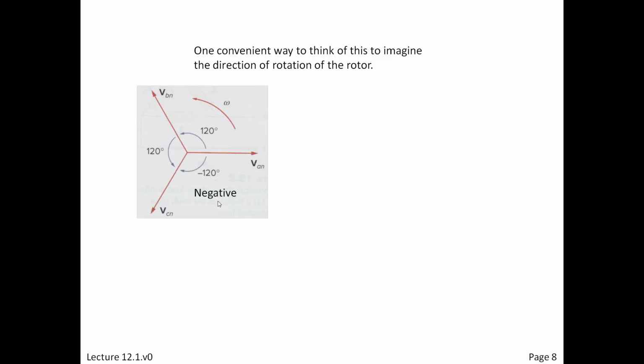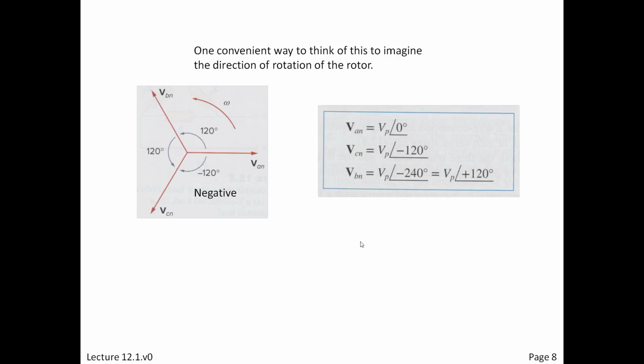So quite simply, if we want the negative rotation, which would be ACB, all of the mechanics are the same. The rotation of this, you can almost think of this as like the three blade propellers in wind generating systems that keep rotating in one direction, and they have 3 big giant blades at 120 degrees. Well, C is the next one to orient. Clearly, all that happened was you reversed B and C. It's the same thing physically you would do on the rotor if you just relabeled the stator connections.